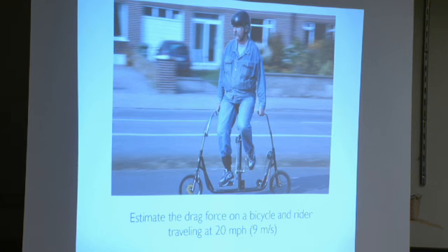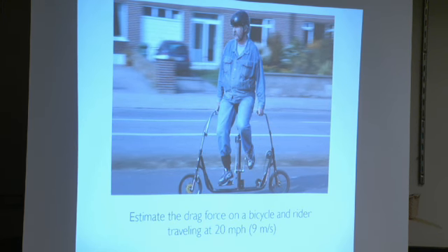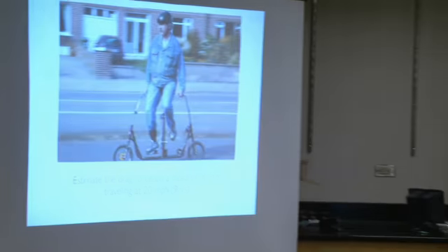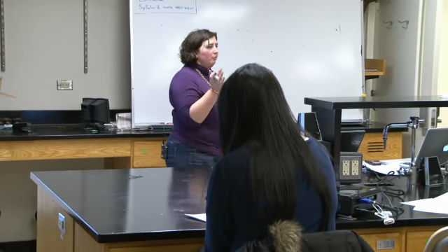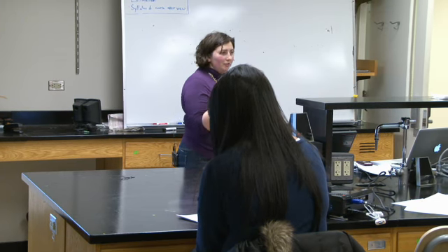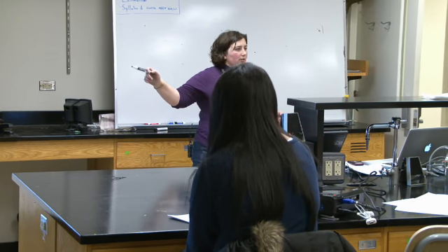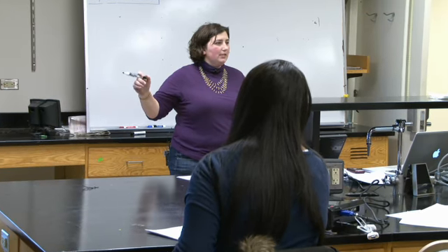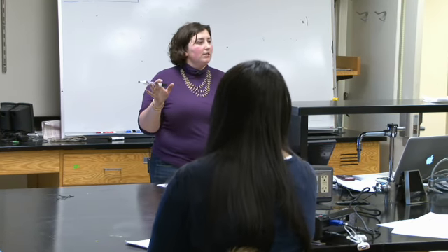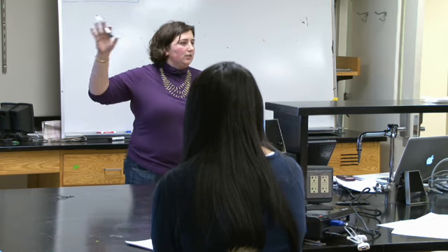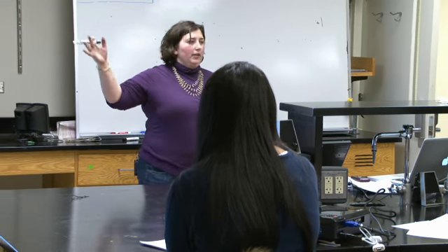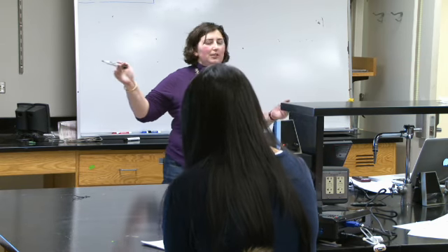So what do you think is bigger? You think the ground is bigger? It's traveling at 9 meters per second. Does anyone have a different approach? So I think the wind is going to dominate, and so you could include the wheel friction, but in an estimation, you want to just look at your biggest quantity. So I'm going to say we can neglect that friction and just focus on the drag associated with that body going against the wind. And this is the question from last year.